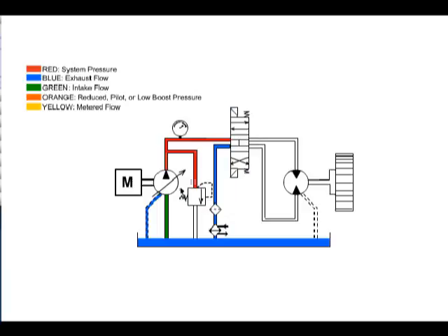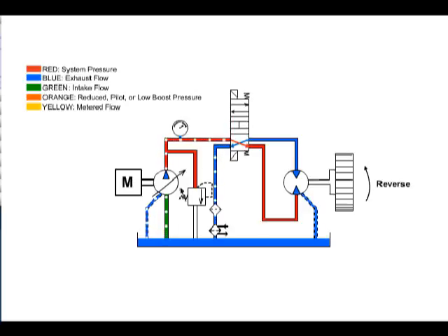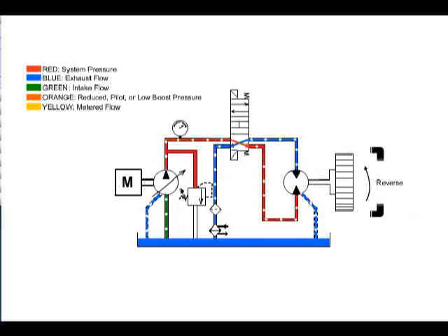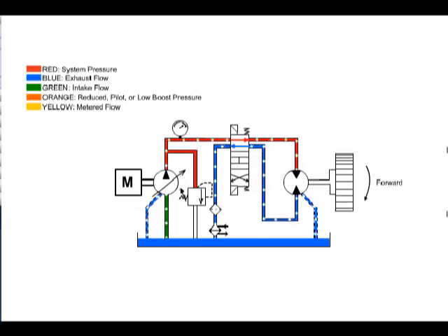The directional control valve allows for forward or reverse direction of the motor and freewheeling of the hydraulic motor when the valve is centered. The filter and heat exchanger will condition the fluid before it returns to the reservoir. The variable pump will now allow for variable output speeds from the hydraulic motor. If the hydraulic motor rotation is restricted or stopped, the high pressure relief valve opens, protecting the system from overpressurization.